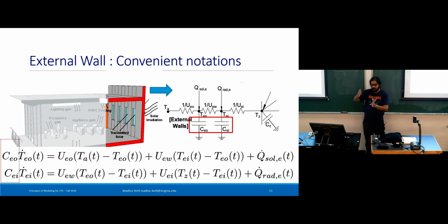We have seen that walls are layers, and so if you prefer, I'm going to treat the first 2 layers as part of my external model of the wall, and the latter 2 layers as part of the internal surface of the wall. Then you can assign them different thermal masses based on the materials of the layers. But the general rule is that the sum of the external capacitance plus internal capacitance is equal to the total capacitance of the thermal mass of the wall. So in simpler terms, in many cases, these two things are exactly the same, but they need not always be the same. Okay? And we will see examples of when they are not the same when you do the modeling.